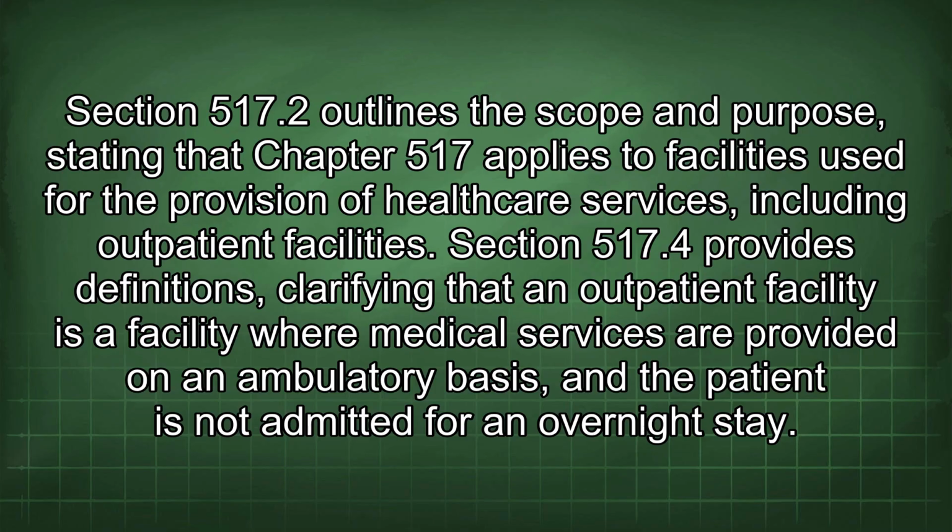Section 517.2 outlines the scope and purpose, stating that Chapter 517 applies to facilities used for the provision of healthcare services, including outpatient facilities. Section 517.4 provides definitions, clarifying that an outpatient facility is a facility where medical services are provided on an ambulatory basis, and the patient is not admitted for an overnight stay.